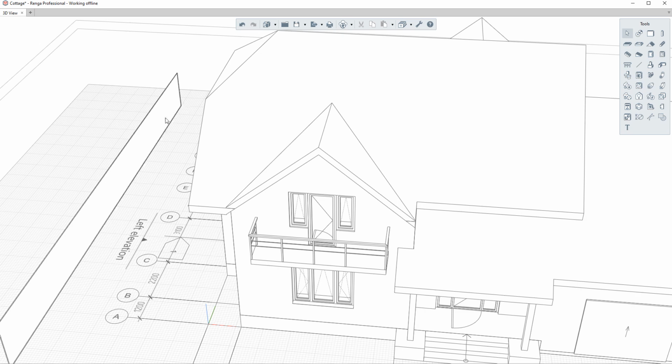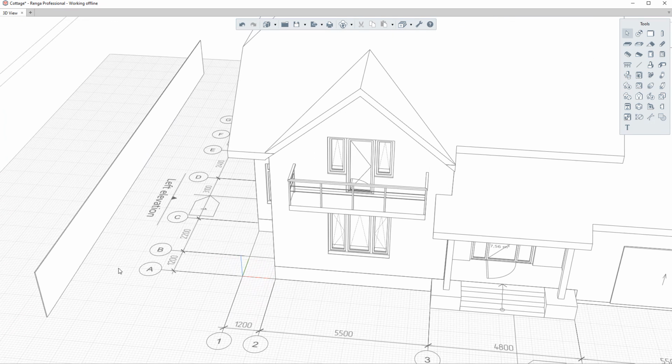The values in the input fields are determined by the measure mode. To get to the measure mode section, you need to right-click to open the context menu. Measure mode can be two-dimensional, polar or rectangular, or three-dimensional, cubic, cylindrical, or spherical.